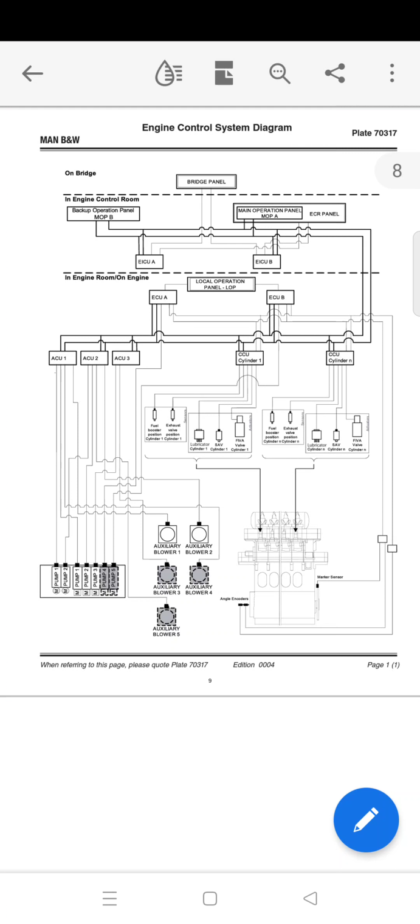The timing parameters for the fuel injection and the exhaust valves are calculated and the pressure set point for the hydraulic power supply is derived. Based on the user input of the fuel sulfur content and minimum feed rate, the resulting cylinder lubrication feed rate for each cylinder unit is calculated. The resulting fuel amount command, the requested fuel injection profile, the timing parameters, and the resulting cylinder lubrication feed rate amount are all sent to the CCU of the cylinder in question via the control network. Likewise, the hydraulic pressure set point is sent to all the ECUs.